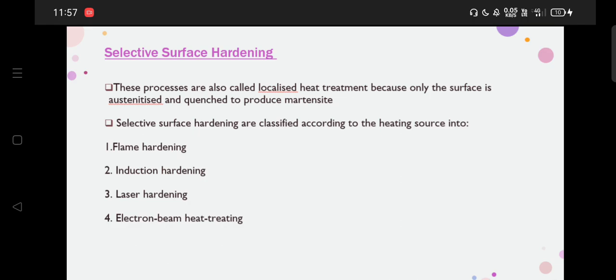Next one is laser beam hardening. Laser beam hardening is another variation of flame hardening. A phosphate coating is applied overall to the steel to facilitate absorption of the laser energy. The selected areas of the part are exposed to laser energy. This causes the selected areas to heat. By varying the power of the laser, the depth of the heat absorption can be controlled. The parts are then quenched and tempered.